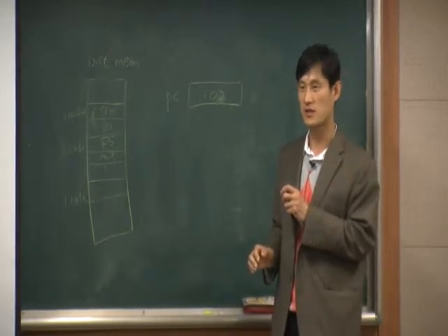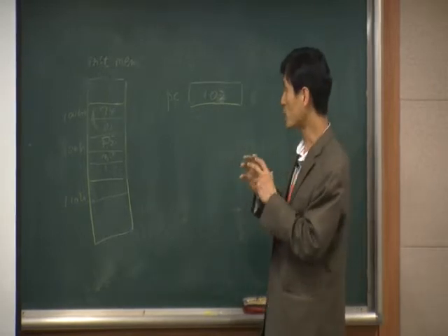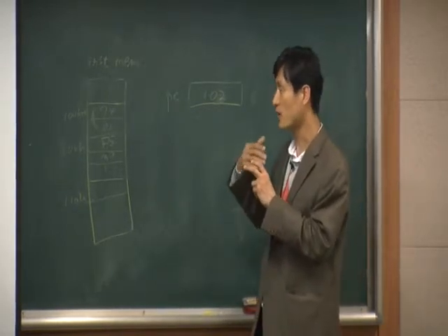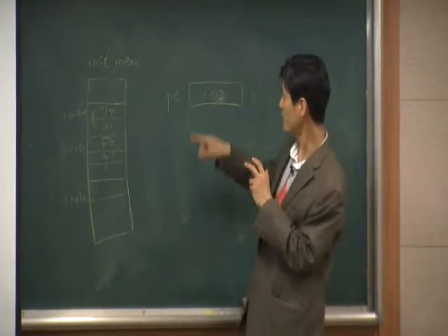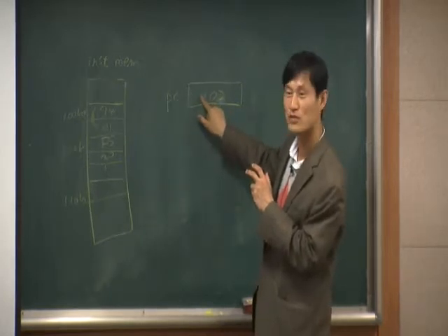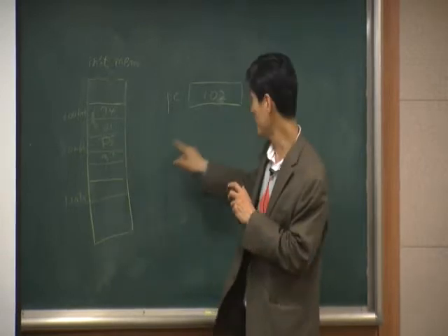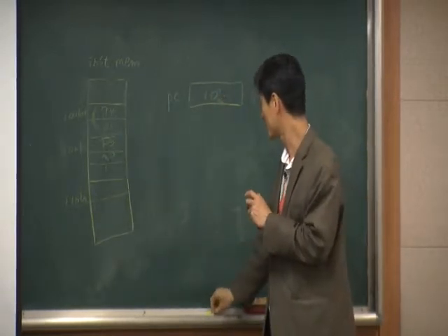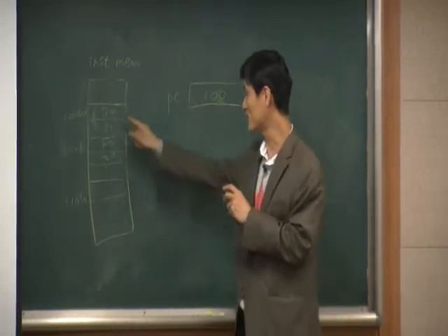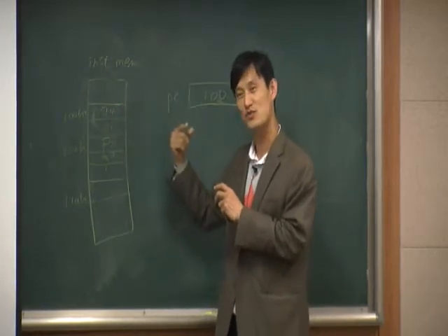Do you understand what I'm saying? So that way, the next time the microprocessor fetches, I have to come to here, and this is the next thing to fetch, right? If this one stays 100, then the microprocessor will fetch this one again and again and again. You should not do that, right?